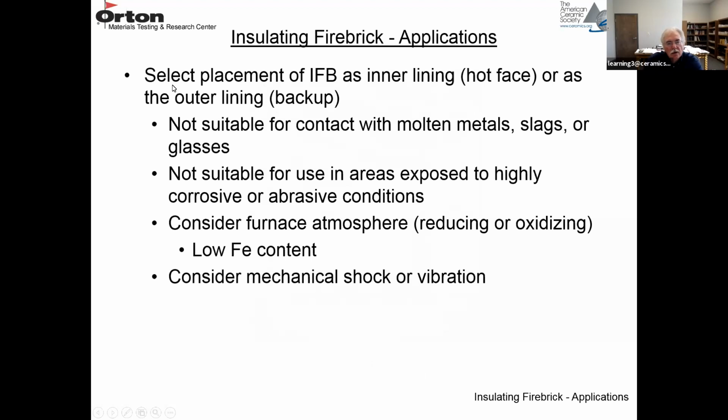So IFBs can be used as an inner lining, hot face, or as the outer lining backup. If they're used as an inner lining, they're not suitable for contact with a molten metal, a slag, or glass because of the high porosity. They're also not suitable for areas exposed to corrosion and abrasive conditions because they're very weak and high porosity.